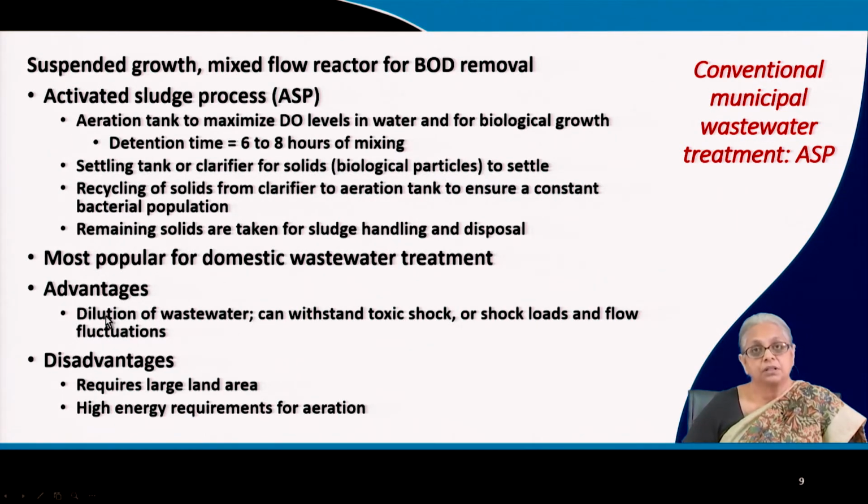The first thing is it allows dilution of the wastewater, and that is very important because this dilution provides a shock absorbing capacity which other processes do not have. So it can withstand toxic shock. Supposing someone in the city dumps a load of toxic material, that will not kill the biological process despite the toxicity of the material. That's because of the dilution.